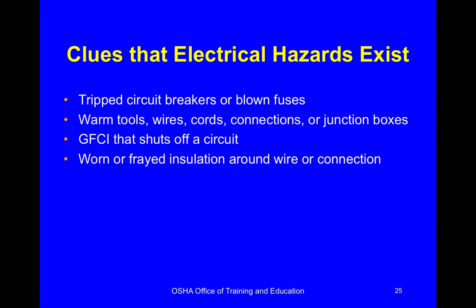So some clues that there is actually a hazard there. I'd already said if circuit breakers are tripping, fuses keep blowing, don't just go put a bigger fuse in to fix the problem. There is a problem with overcurrent, okay? Or there's a fault to ground. If tools are getting warm, connections, cords, wires, boxes, any physical devices or mechanical devices, that's a clue that something is wrong. Remember, heat is going to generate more resistance, which will generate more heat. It'll snowball into a fire.